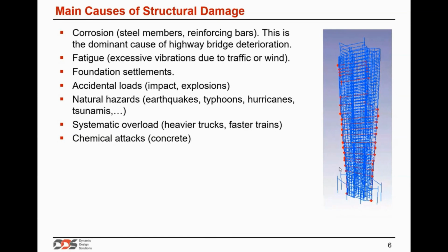It is okay to do that with a coarse model, because it will have an overall impact on the structure. And if there is damage caused by an earthquake, it's probably going to be detectable through a coarse model like this. But it will not be possible to detect damage in one steel member or in some part of the structure. So you have to adapt the simulation model also to the type of damage that you are trying to detect.